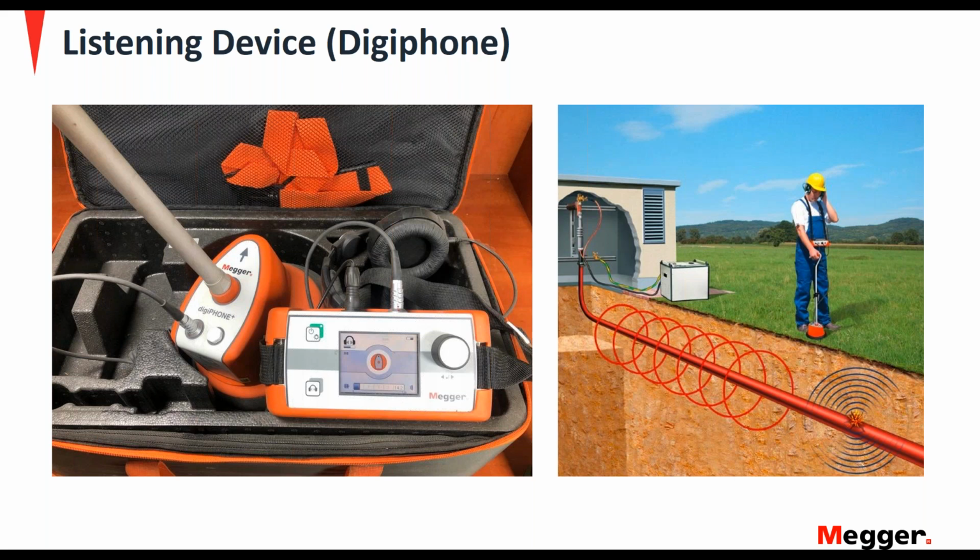Sometimes, even with a lot of joules, we have what we call a quiet fault. When you're standing above it, you can't hear or feel it. Also, sometimes the arc reflection method doesn't give us a distance. In that case, we may have to walk the entire cable path. We know the fault is on the cable somewhere, but we could have a 2,000-foot cable and we don't know where the fault is. In cases like this, the digiphone is invaluable. It's really our friend. It's going to save us time. It's also going to reduce the number of thumps we have to put into that cable.